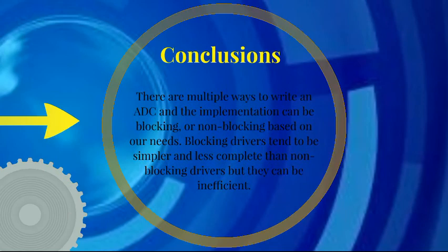And in conclusion, as we have seen, there are multiple ways to write an ADC driver, and the implementation can be blocking or non-blocking based on our needs. Blocking drivers tend to be simpler and less complex than non-blocking drivers, but they can be inefficient. Non-blocking drivers allow our code to run while the driver works, but the application code still needs to check and own the status, which in itself is inefficient in a polled implementation.